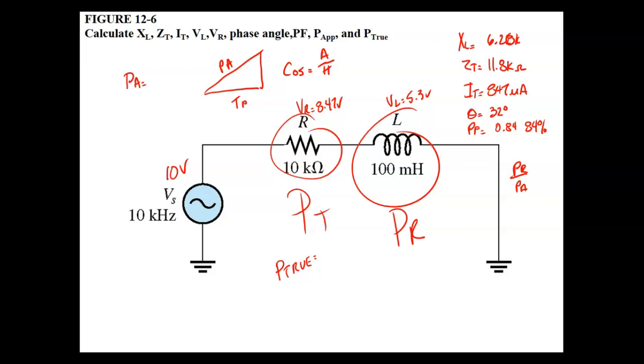So over here on this guy, I'm using a resistor. I forgot that one time, and of course, as soon as it glowed, it got my bulb, because as soon as that current starts flowing through that gas, the resistance of the fluorescent bulb itself drops down, which would cause the current to go up, right? You understand? Unless I have something that does what? Drops the voltage I don't want. But I don't want it to produce power. I don't want it to get hot. I don't want it to cost me power. So that's why we have ballast in those things.